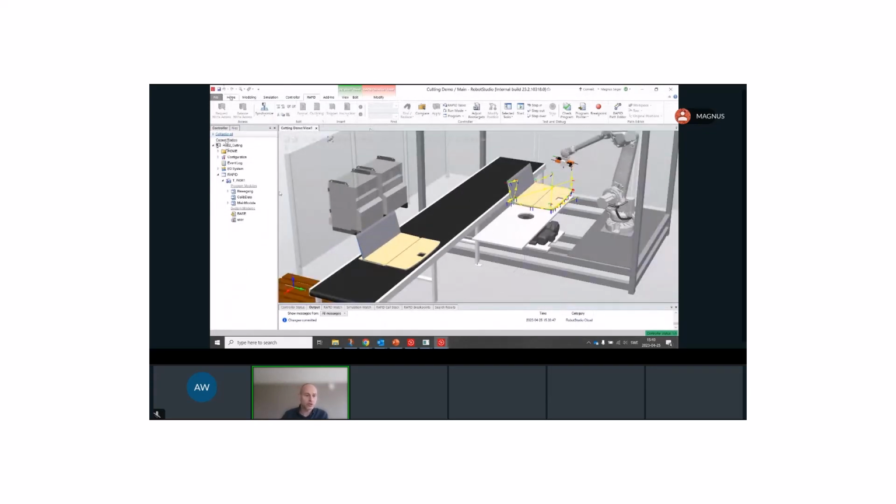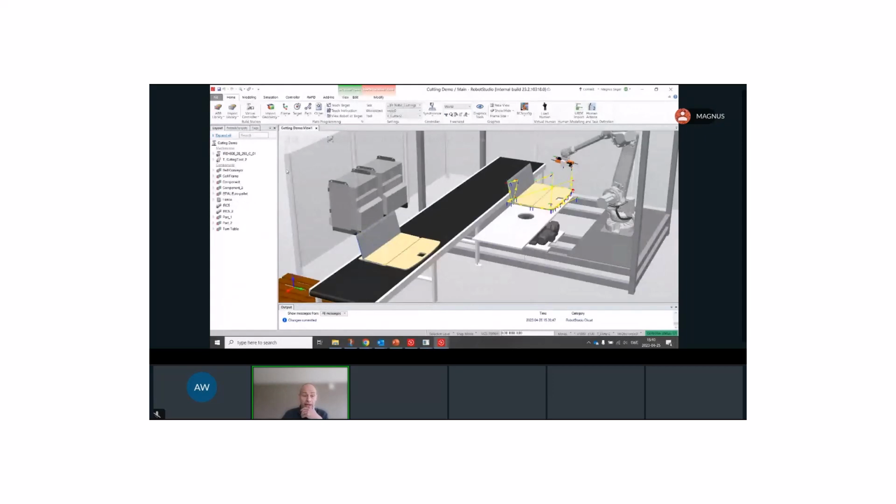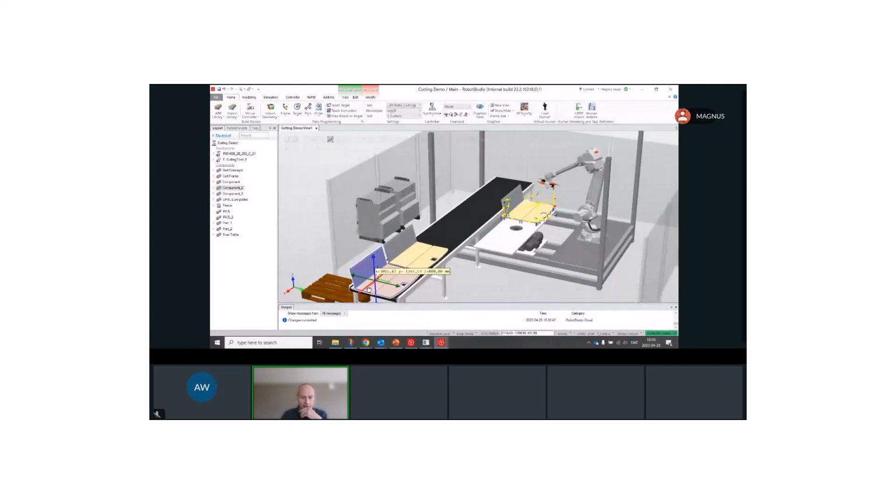I can of course do changes to the environment, the station, to the layout. So let me do that as well. I'll make a copy of this piece. This is the guy. I will just drag it a little bit like this. So we say that we have another instance of this one. I'll save it. I commit it. I push it up. You have to label it as an added part. Okay. So that means not only the Rapid, but also the station layout will be now stored in the version control system.